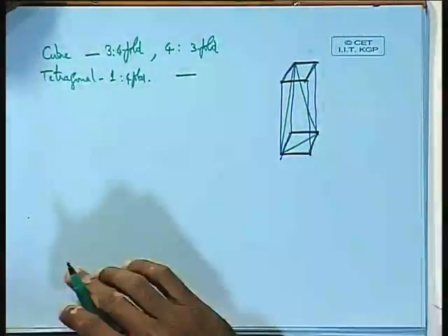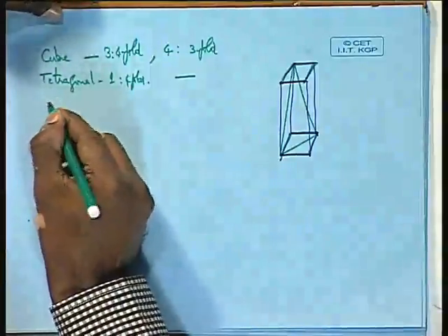It has no 3-fold. So just by a simple tension of a cubic system, making it a little bit elongated, that means the C by A ratio has been changed from 1 to either less than 1 or more than 1, immediately the symmetry of the system changes. And that is the characteristic of a tetragonal. And what is the next one? It is the orthorhombic.